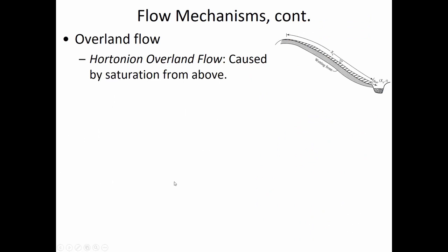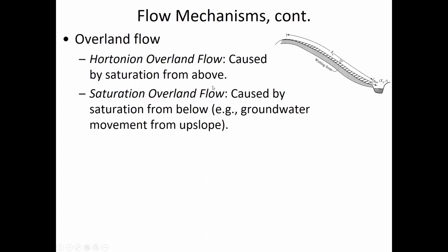So the flow mechanisms, overland flow is going to be wetting at the surface that makes its way to a channel. And as the water is flowing over the surface, of course, there's also some infiltration that's occurring. And so you'll notice here this figure is showing a wetting front that's going progressively deeper into the soil. But there is some quantity of water that arrives at the surface due to rainfall and flows over the surface towards the channel, and that's the fastest.